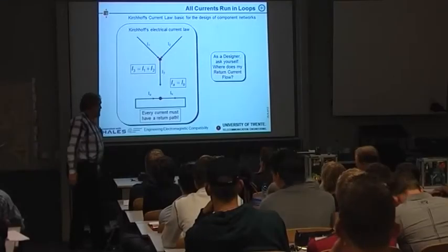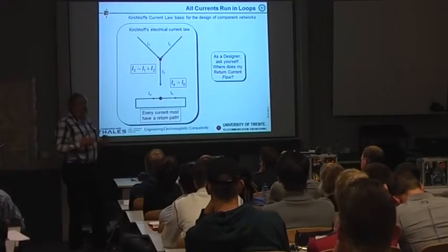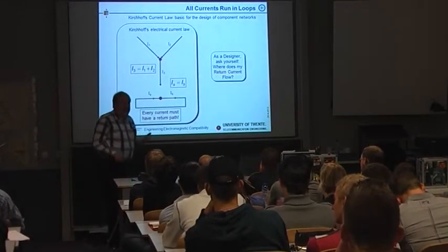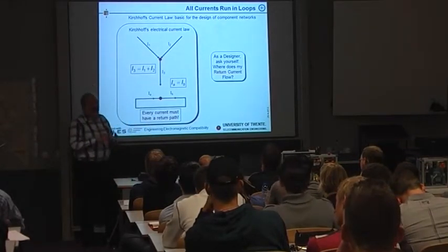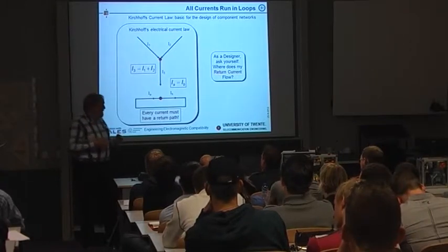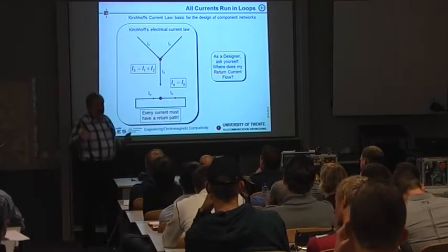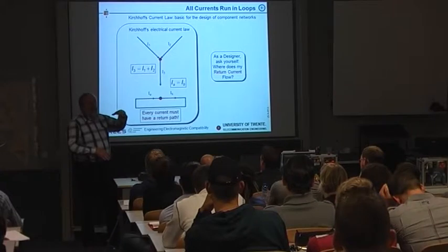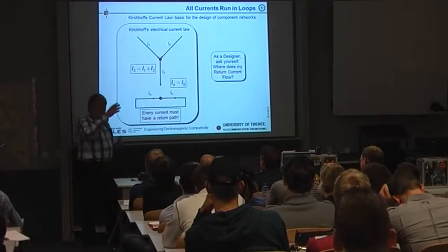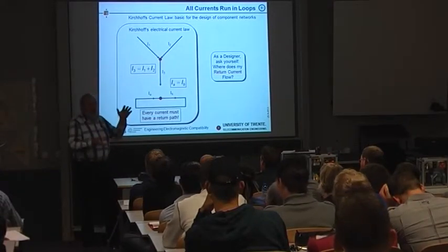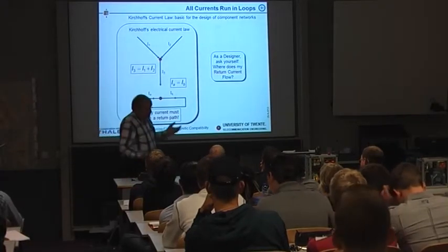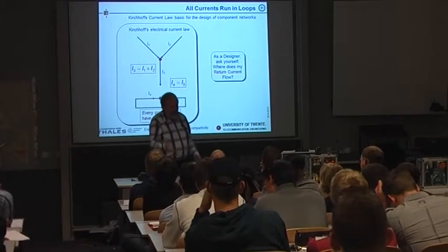Electronics in cars, a lot of cars, metal cars, use the chassis as a return, but it's there. You have to know it's there, and if you have high frequency fields, and the wire that's feeding it from one side is not against the metal of the car, then you have a big gap between your outgoing wire and your return flow. If there's a big gap, you create a magnetic field, or you create electric fields. If you put them together better, I'll show you that.